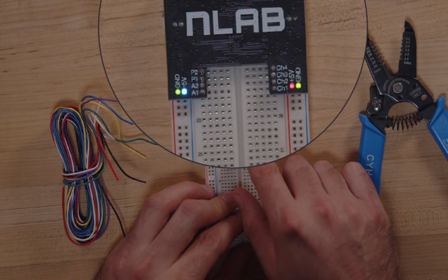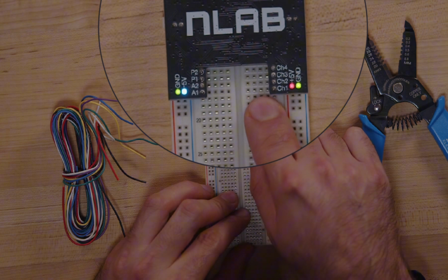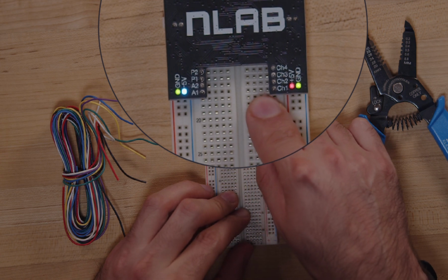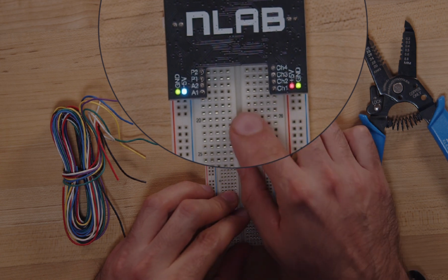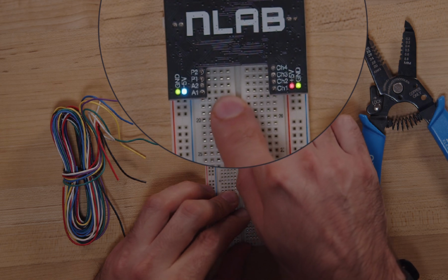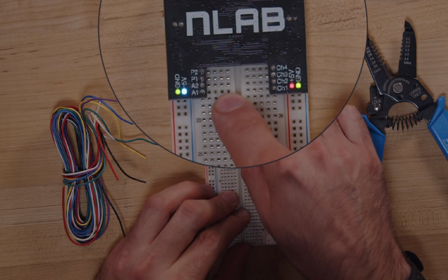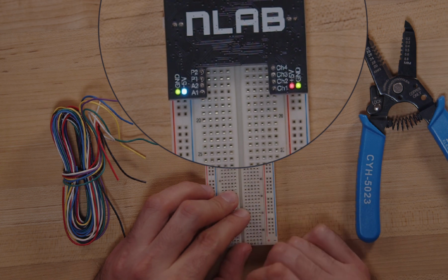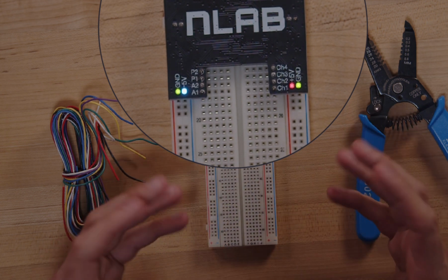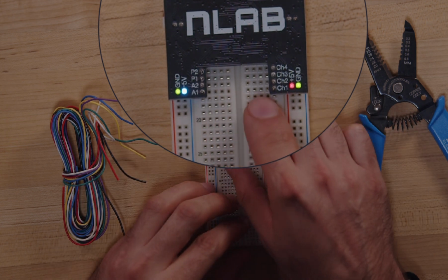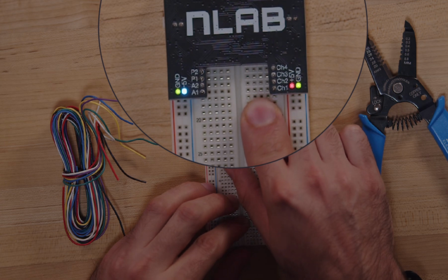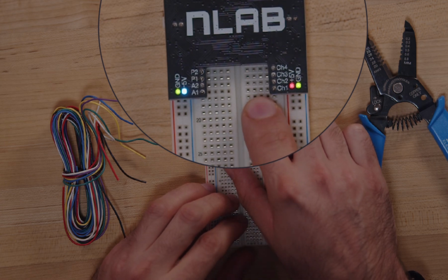Putting a wire from our circuit into the CH1 row means that we'll be reading something about the circuit on channel 1. Putting a wire into the row for A1 can take a signal out of A1 from the signal generator and put it into our circuit. For instance, I could use a wire to connect A1 directly to channel 1, and then we can turn on the signal generator in the app and see the signal.